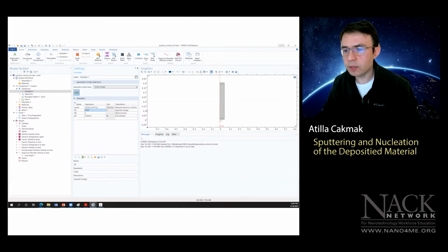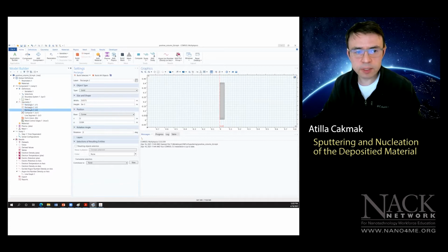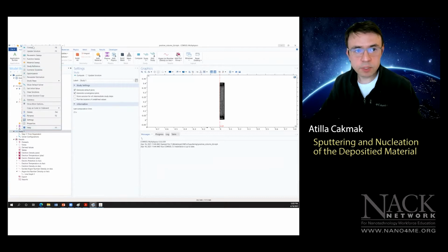So what does that mean? We're going to still ground this electrode and we're going to apply 10 volts to this electrode, okay? So just 10 volts. And we're going to feed in argon, that's the gas pressure inside our chamber. We're going to feed in 0.5 torr of argon, okay? That's kind of a huge amount, I know, 500 millitorr, but we're going to feed in with that. And let's go to geometry just to make sure. Yes. So this whole chamber is like 0.4 meters in total, from end to the start. And we're just going to simulate this very quickly.